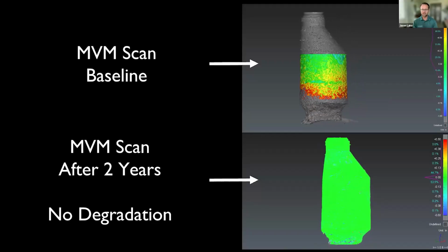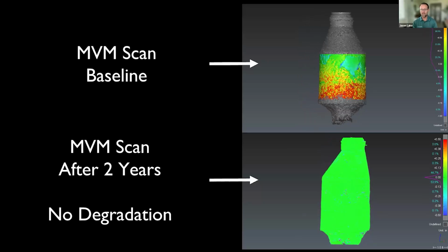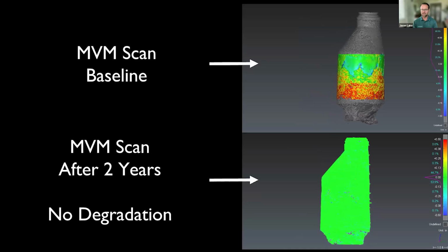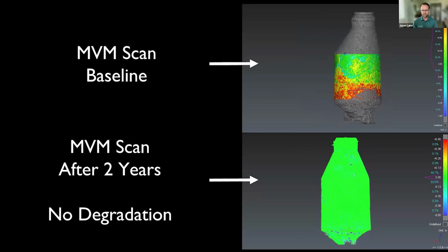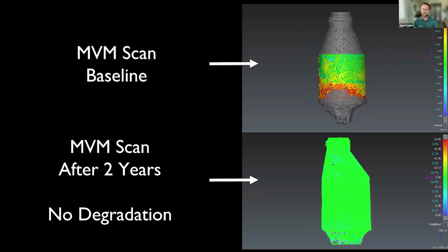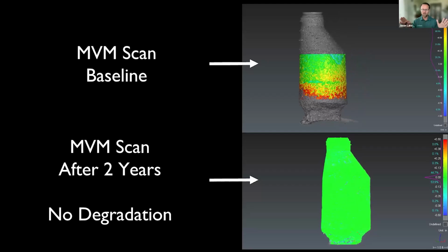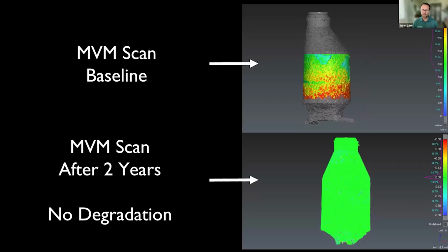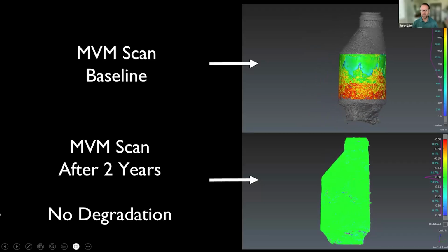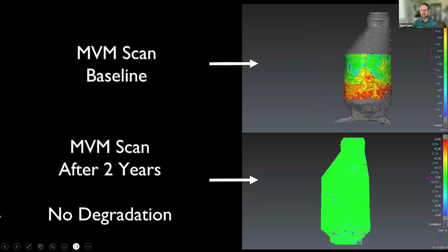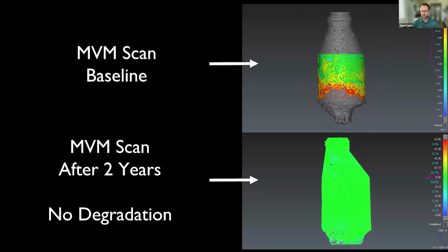Up top, this is the wall score analysis from that manhole we just saw. And you see, I got red, I got blue, I got all the things that we're looking at that's going to scare us. That's going to say, hey, we got to do something about this. But incredibly, the bottom is the analysis of, let's call it year 0 versus year 2. So over this 1, 2, 3 year timeline, those walls are not changing at all. And what that tells us is that, yeah, it's an ugly manhole, as you would expect anything in this collection system that's been around for 60 years.